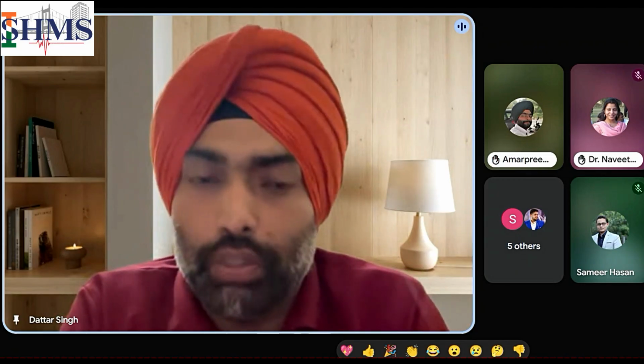I was shocked to see this much variation. Then I studied some literature, and it is an established pattern. Damping ratios vary if we vary even one particular parameter used to obtain them, even the type of excitation. Then even the type of measurement sensor, even the type of identification algorithm. So damping ratios are quite sensitive to all of these parameters.